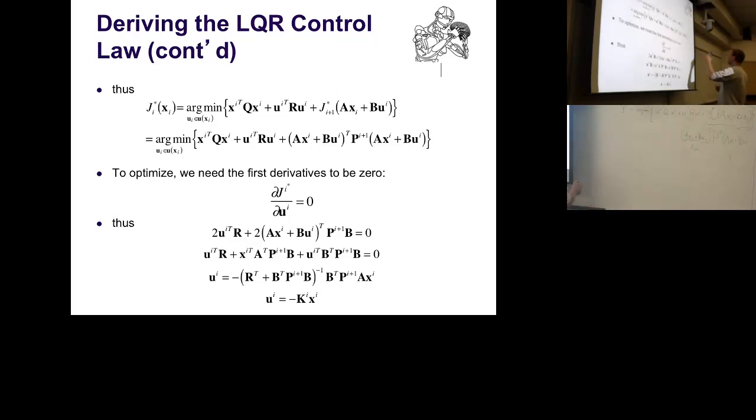And now, given that I have that and I want to minimize it, I have to just take the derivative of J star at time step i with respect to the current motor command u_i. And now you get, at this point, most likely the idea why I chose a quadratic optimization criterion. So now I basically have to take every derivative with respect to u_i, and then I want to solve for u_i afterwards.